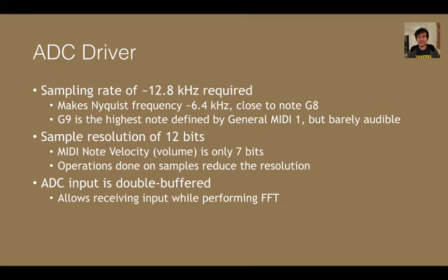The ADC input is double buffered, meaning that every time a sample buffer is filled, it is swapped with another one to prepare to read more samples from the ADC. And this allows the microcontroller to receive analog inputs while performing the FFT.